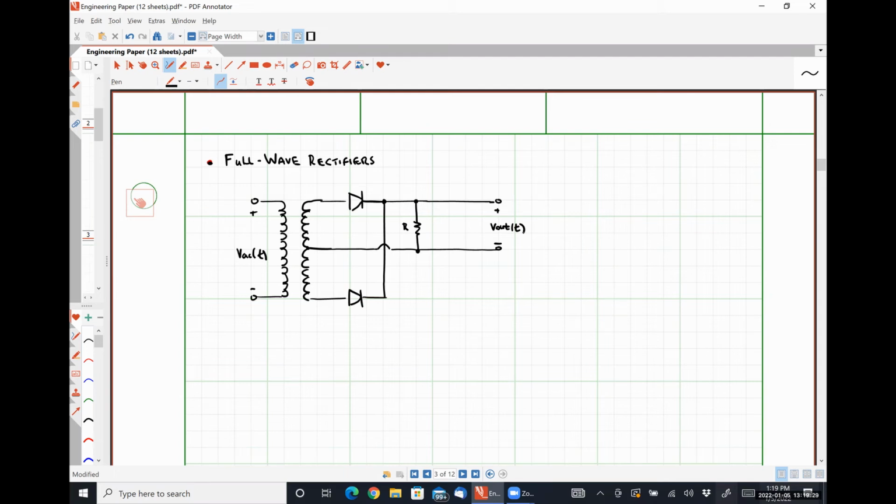Okay. Center tap transformers are very, very common in households. That's how we take 240 volts, which is what things like ovens, probably hot water heaters, and maybe dryers in our homes use, and step it into two identical 120 volts to go to all of our microwaves, lamps, and all that kind of good stuff.